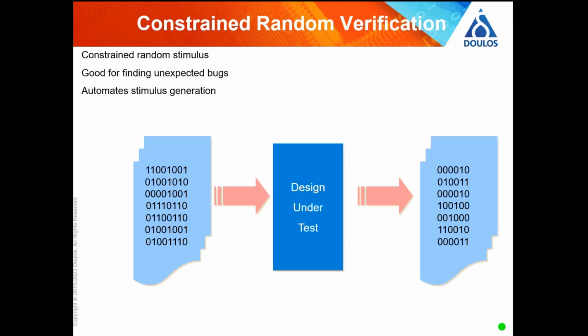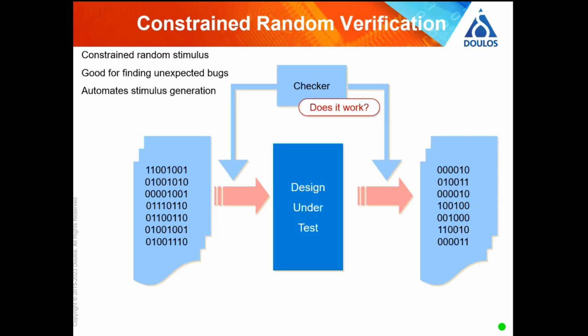So there's a very simple example of why random testing is not better than, but should be done as well as, so-called directed testing. Another one is you can just set it running and it can be finding bugs. If you've got enough licenses and enough computers, you can just set it running and off it goes, and it might be doing useful work. There are some more things to say, however.